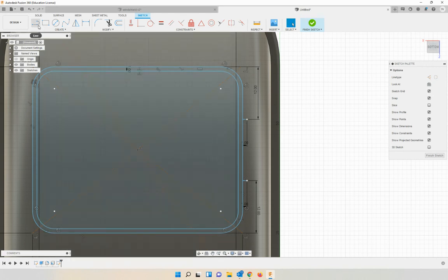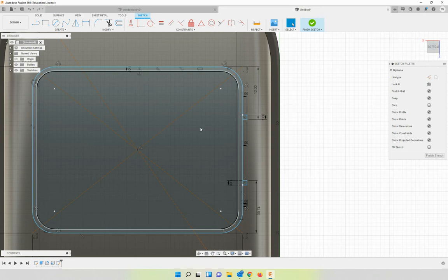Let's complete the rectangles with line tool. In point, up 1 millimeter, click, and in 1 millimeter, click. There's that dimension. All right, now these are the inner sides that we position. Click down 1 millimeter. This is important. And over 1 millimeter. All right, escape out of the line tool, and I have my two notches in place.